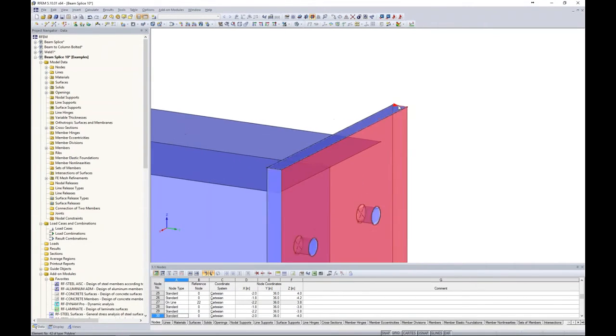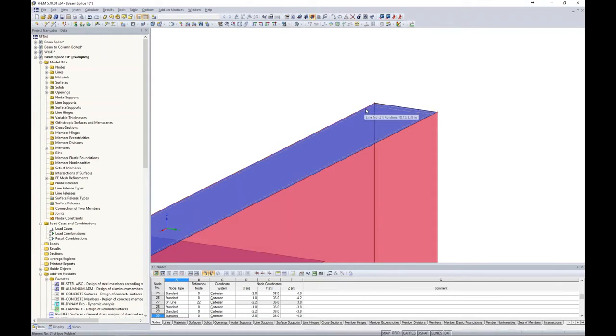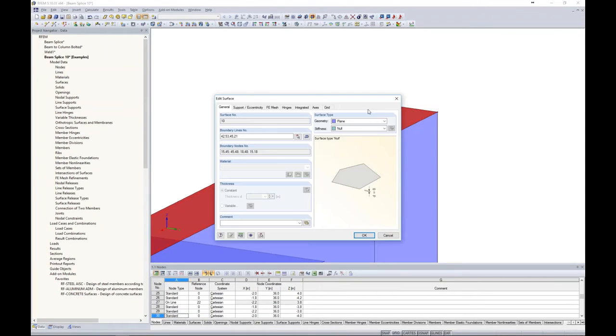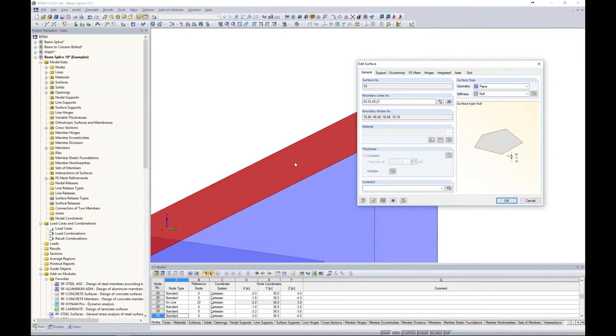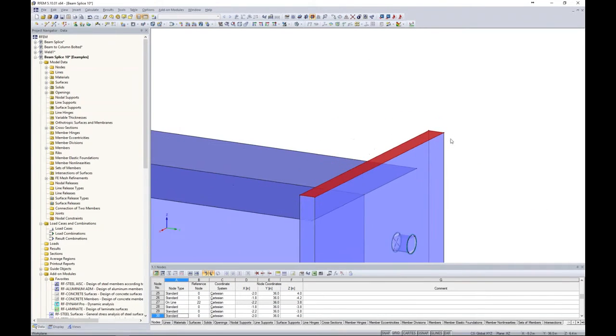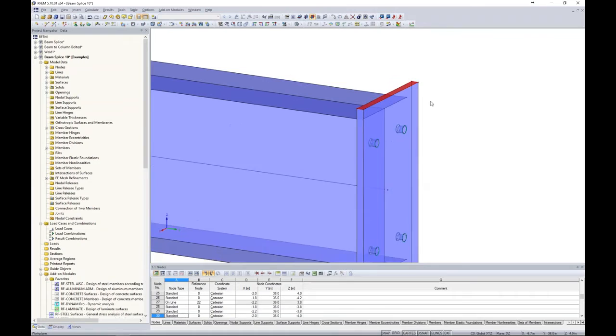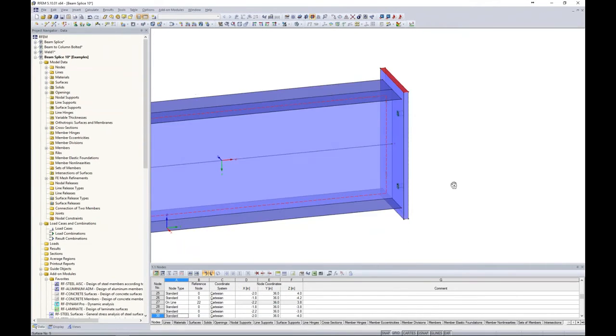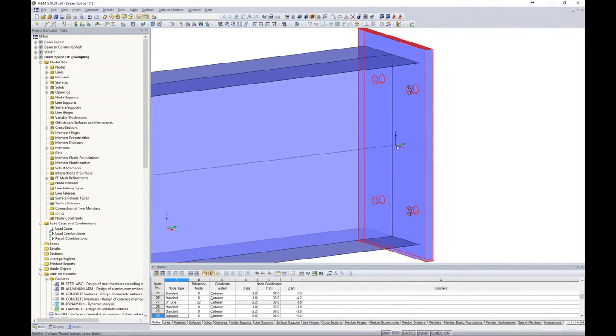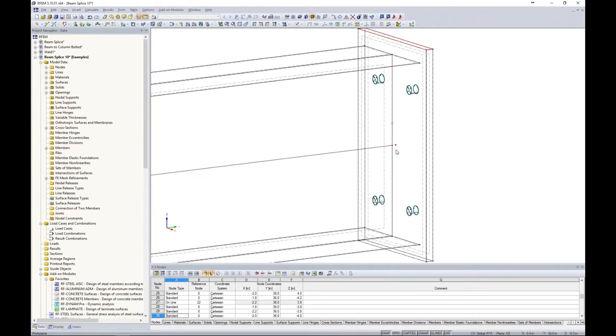But you'll notice that at the top, these narrow sides, I still have my surface elements here defined as null. So around these smaller edges, we're going to keep all of those with 0 stiffness. So we currently take a look at this solid, and it's indicated, if we turn this into wireframe, it's probably a little bit easier to see by this purple node right here in the middle.